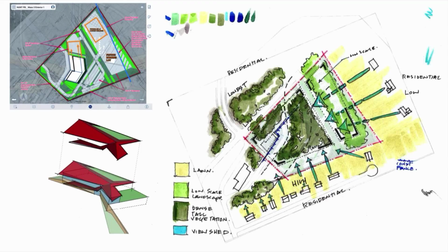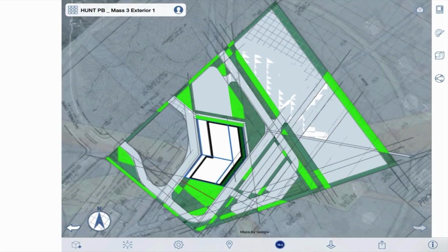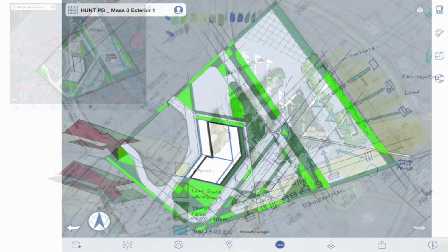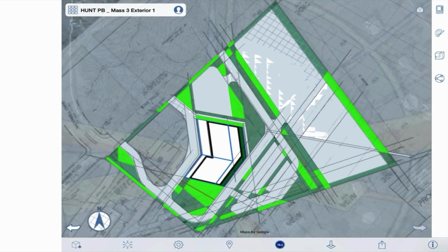Meanwhile, again, to go analog again, I may be doing a series of what you see hand sketches, or in the upper right-hand corner, taking the FormIt model and creating a surface and using that to subdivide the surface with lines and sort of draw right on that surface to send that back to the team and do a series of sketches about, in the lower left, maybe an idea about the roof of the building. This is that subdivided surface in FormIt, which I gave an extrusion to, and I was able to basically draw on and copy and do a sketch